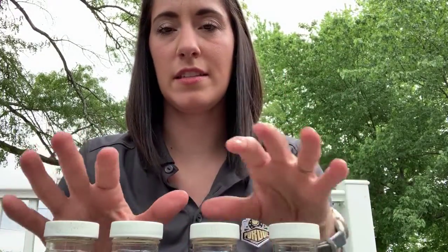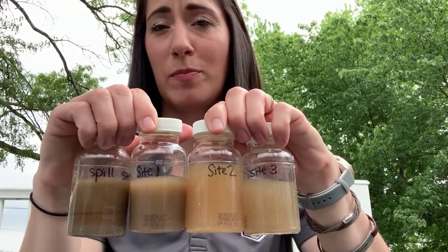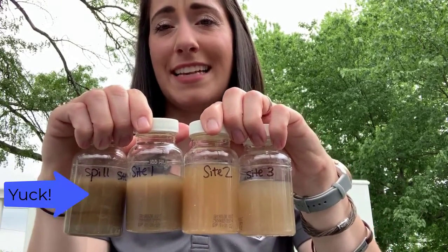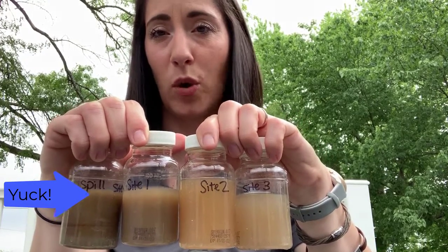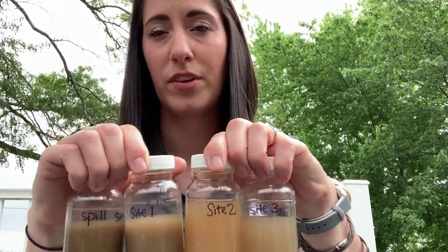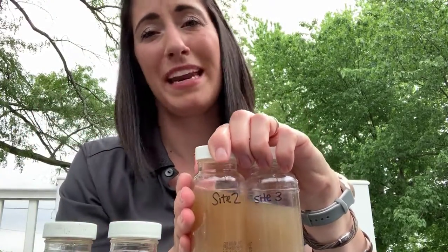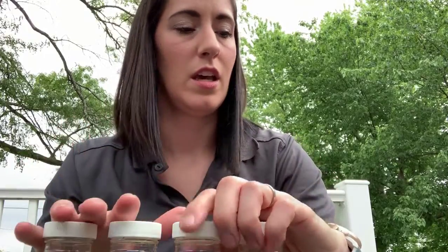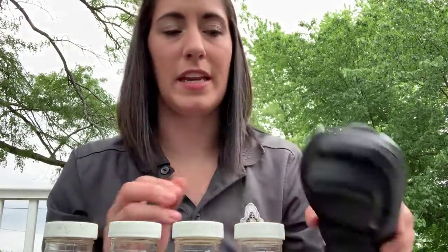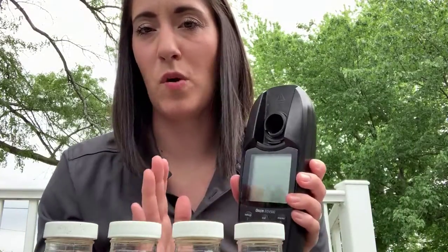So when we look at these, we're going to say, even just visually looking without taking our turbidity measurement yet, we can say that site 2 is probably the best place to locate our filter if we want to get as much contamination out of the river as possible. We don't want to put it in up here at site 1, or we'll have missed everything that already made it past site 1. So in order to check our turbidity, all we have to do, this works in a really simple way.